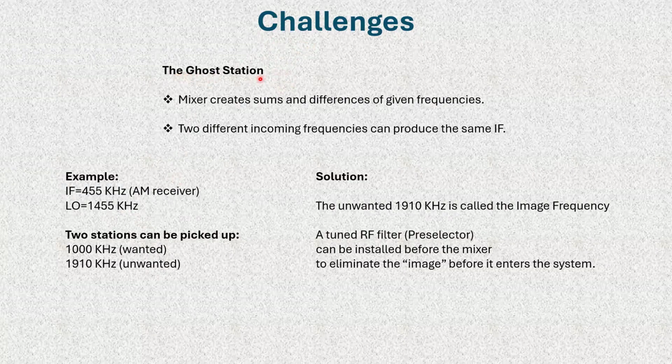Here's the concept of a ghost station. Mixer creates the sums and differences of given frequencies. Two different incoming frequencies can produce the same IF. All right. I put the accent in the wrong spot. Two different incoming frequencies can produce the same IF. Not only the one that we want.